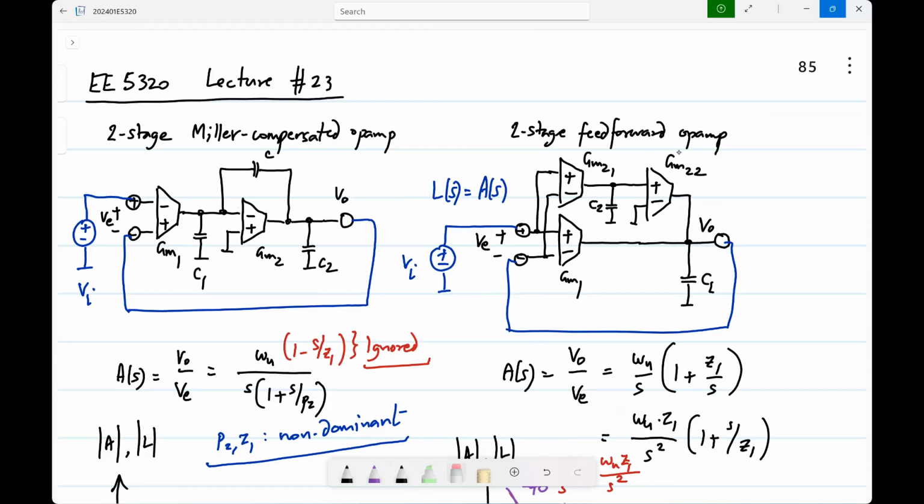Somehow, one way or the other, you should have only one stage in feedback. If you have multiple high gain stages and a single feedback loop around all of them, it tends to be unstable. It may be outright unstable or it may ring heavily. So typically, in any stable feedback system, even if you have multiple stages, there will be one overall feedback which is taking advantage of the very high gain.